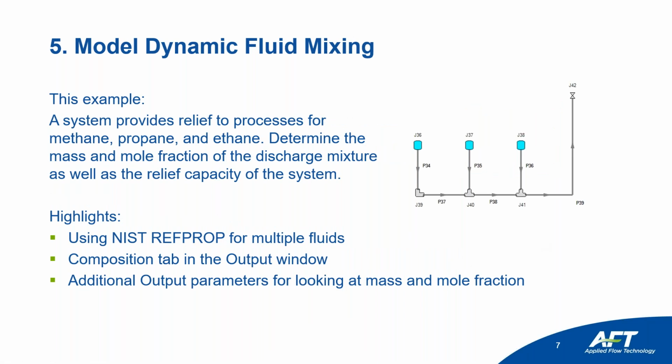All right, the next feature, this is unique to AFT Arrow, is the ability to model dynamic fluid mixing. So in this model over here at the right, each one of these tanks is going to have a different fluid in them, and they're going to combine in each one of these pipes. And our software is able to calculate the mass and mole fraction as they combine into one pipe.